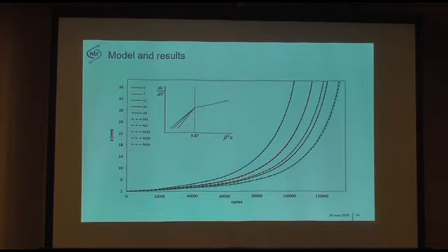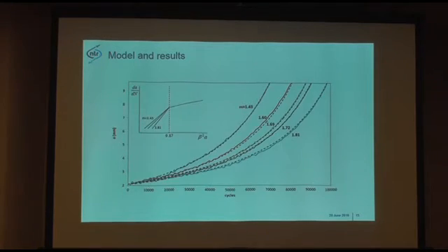So you can choose the slope here, and otherwise everything is fixed. So this is the model, and these are the curves, and you can see the model is the dotted line, and you can see all the models are on top of the measurements. And when you go to only 2 millimeters to 10 millimeters, here you can fit the crack length data, not the derivative of that, but you can really fit the crack length and obtain the exponents for every sample.